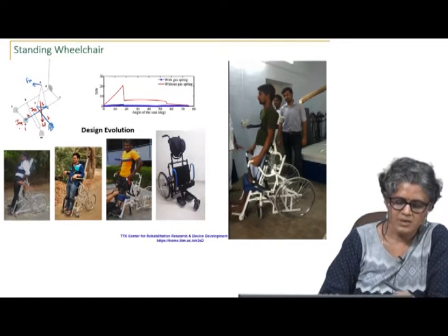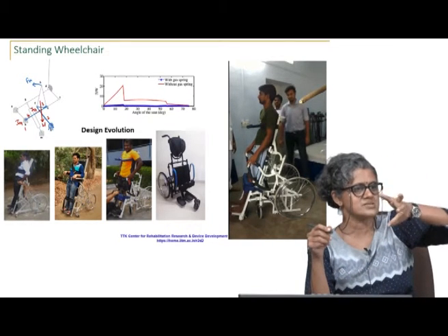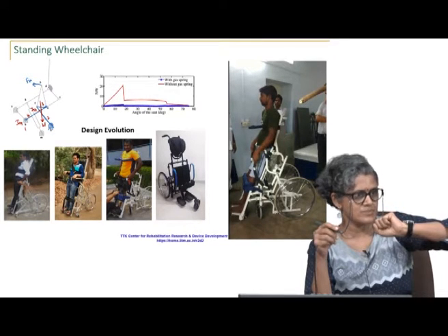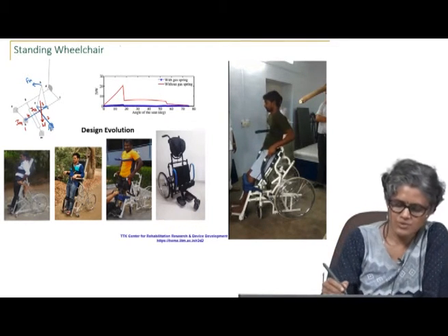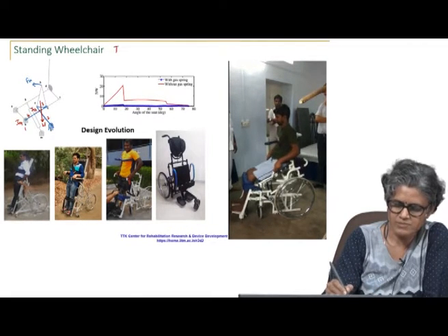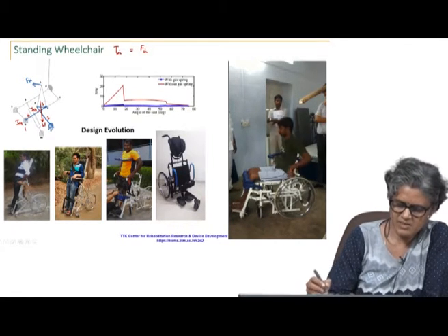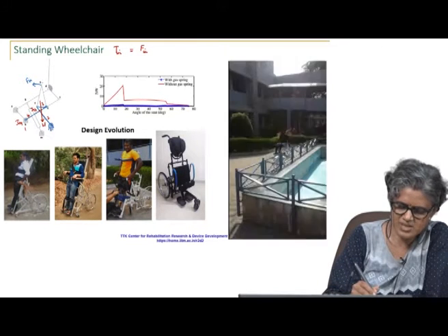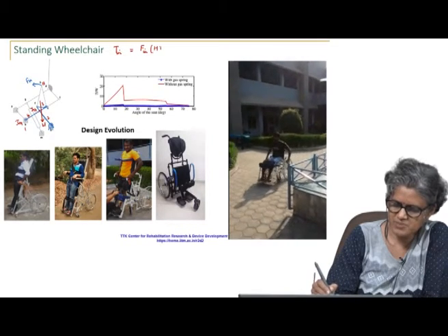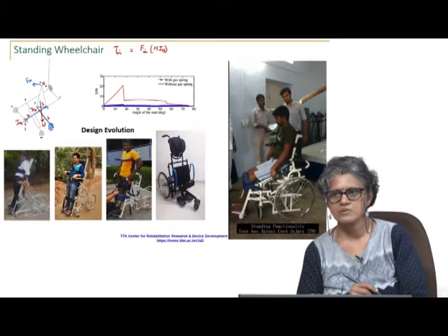Link 3, I can consider it as rotation about this fixed pivot I13, the motion of link 3. So, the torque that is being applied, the input torque, is F_in times the distance. Say this point is H, the distance from H to I13, that is the input torque that I can apply.